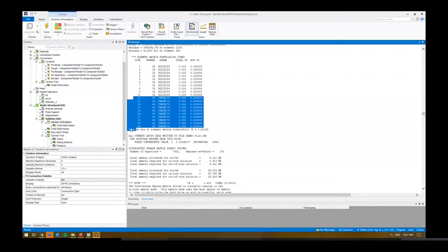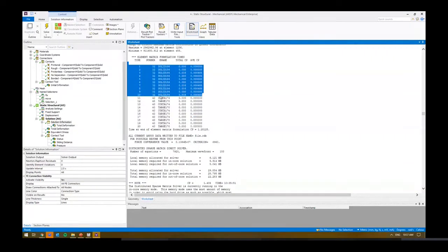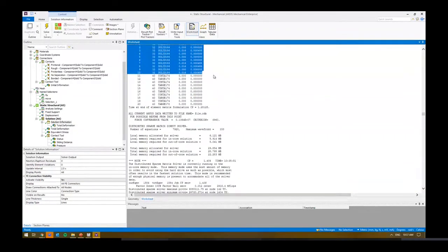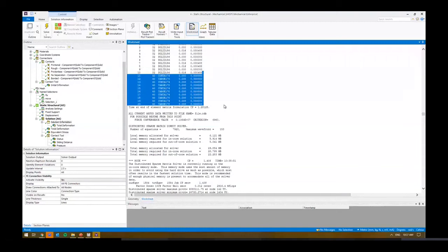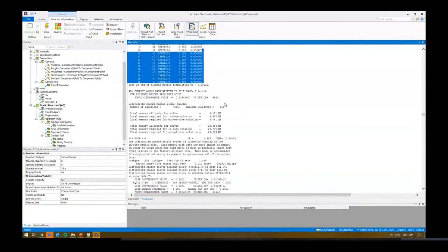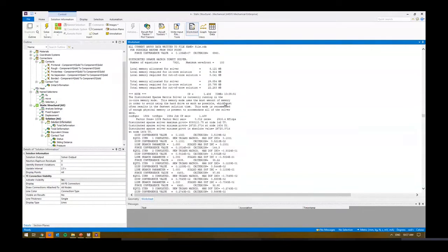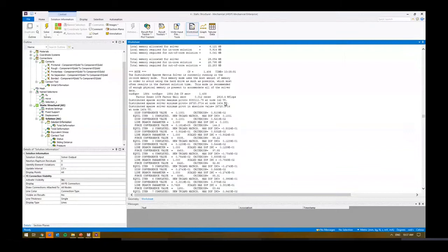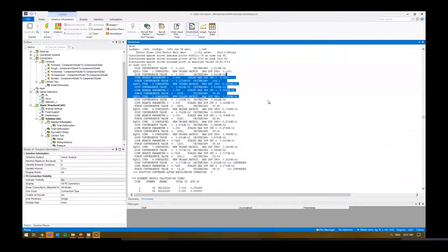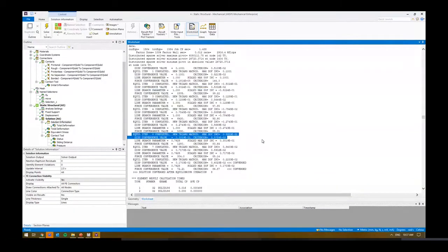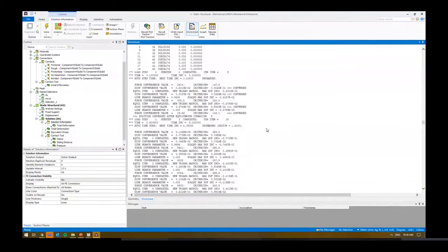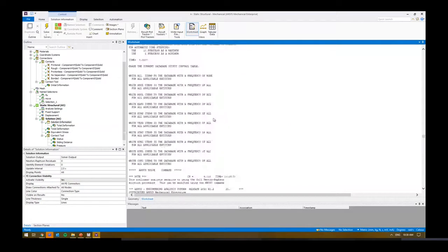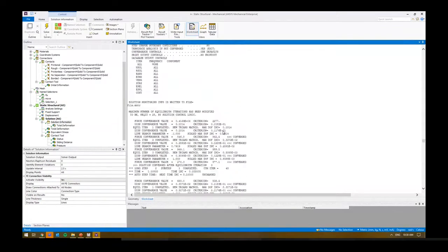So remember, there's like a skin of elements on top of the actual visible mesh that you can see, and these elements transfer the contact, right? Transfer loads from one to the other, and then depending on if it's bonded, frictionless, frictional, the load transfer is different, right? Do we get just direct transfer or do we get some shear as well? We've got some equilibrium equations, right, that are being solved. And we can keep on going, right?